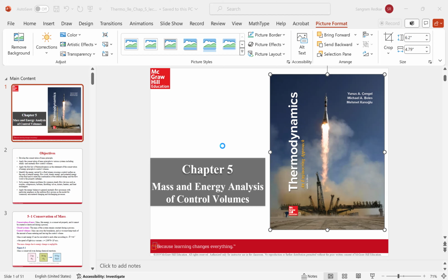Moving on, why is this concept of normal very important? Please understand, fluid does not flow perpendicular to the area. Fluid particles can flow in very many different directions. But to find out the flow, you need to find the velocity which is perpendicular to the area. So that's why you need to take the projection, and the way we take the projection is by taking the dot product with a unit normal.